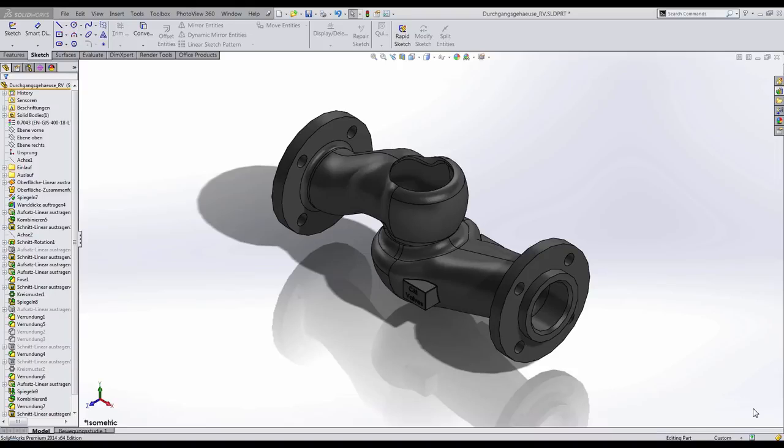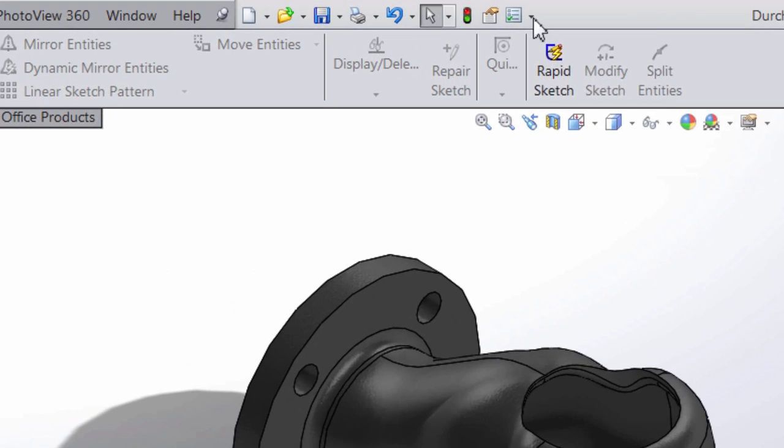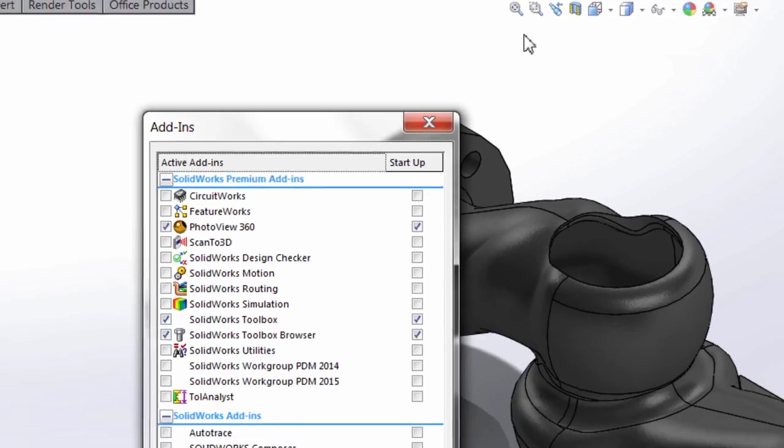When studying internal fluid flow using SOLIDWORKS Flow Simulation or Flow Express of parts or assemblies, we need to create lids so that we can apply boundary conditions. SOLIDWORKS Flow Simulation can automatically create lids. To do this, we need to activate the add-in for SOLIDWORKS Flow Simulation.